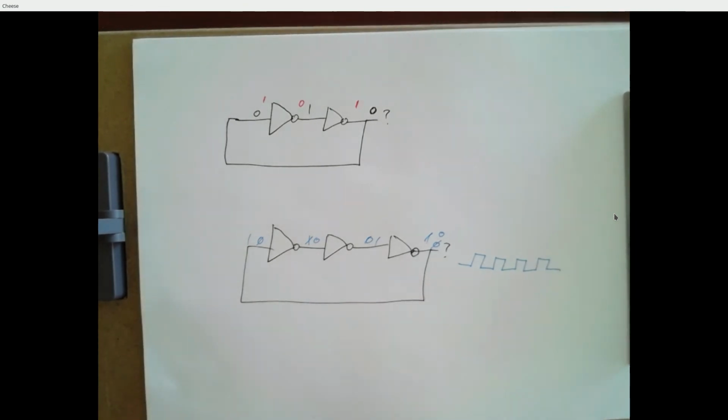And if you build this with 3 inverters on a proto board and you hook up an oscilloscope and you're good at looking at what's going on, you'll see an oscillating output. And the time it takes to oscillate will be 3 times the propagation delay.